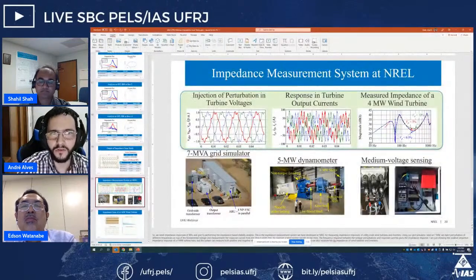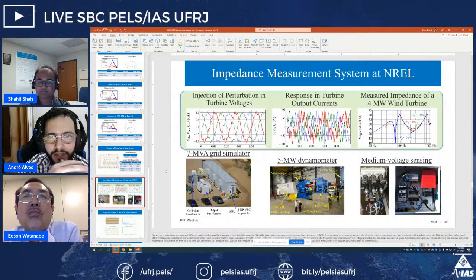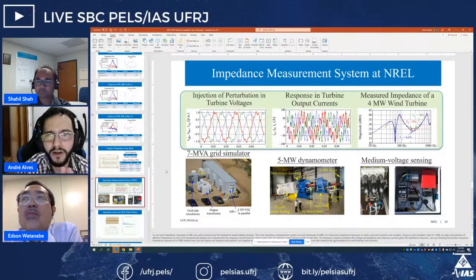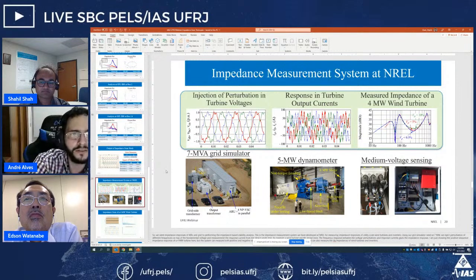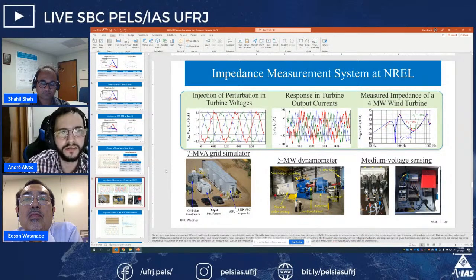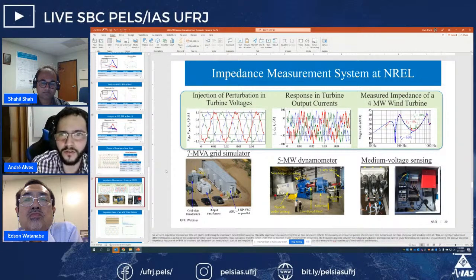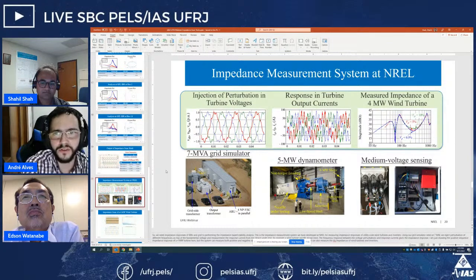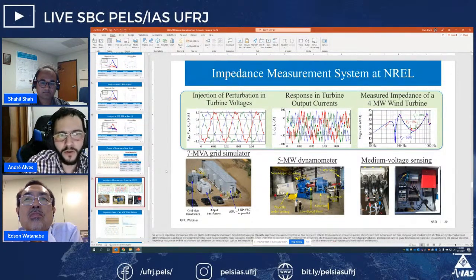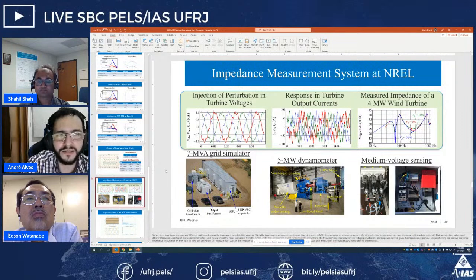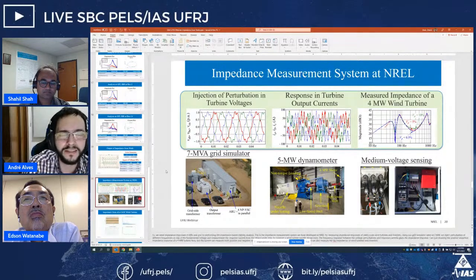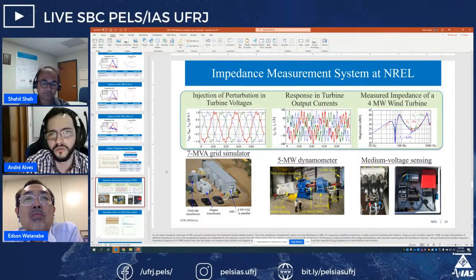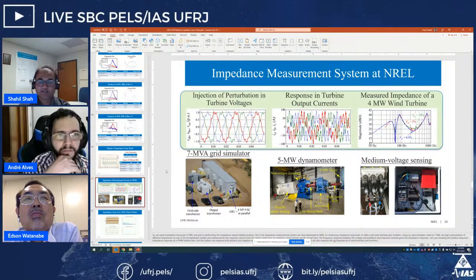Yeah, that one. So basically, if you have a voltage disturbance at a particular frequency, you're going to have a particular current from that inverter at that frequency, right? And what defines the magnitude of that current harmonic is the impedance seen by that particular, in this case, wind turbine. My question is, what is the solution for that particular problem? I do think it is a control solution, but what exactly in terms of control should you implement to mitigate this? Yeah, so that's a good question.